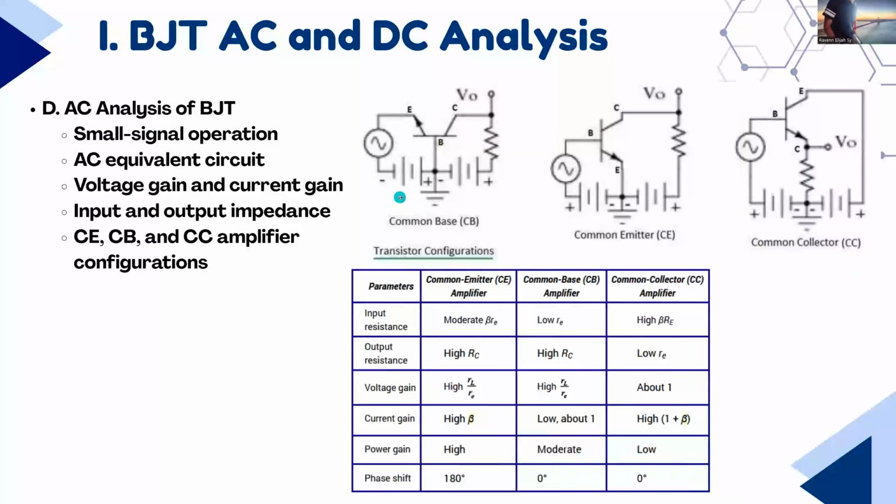Yeah, here. Like I said, we have amplifier configurations. Common emitter: input is applied to the base, and the output is taken from the collector. It provides high voltage gain. Next, the common base. Input is applied at the emitter, and output is at the collector. It offers high voltage gain, but a current gain of less than 1.